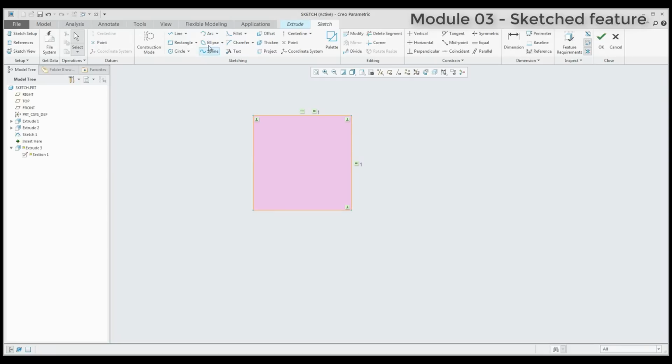And you can use this function again if you work with an arc, for example, and you specify this one, and then you need to create another shape here. You can use the divide function and select divided points, for example, like this, and then you can delete and add another shape here. Yeah, it depends what you need and how you would like to specify. And then again, delete the unnecessary line. Create the dimensions and finish your shape.